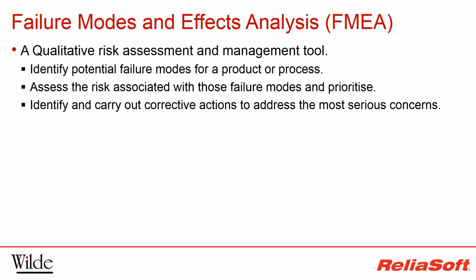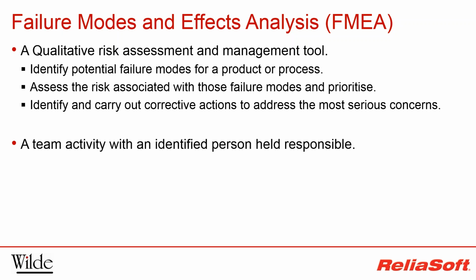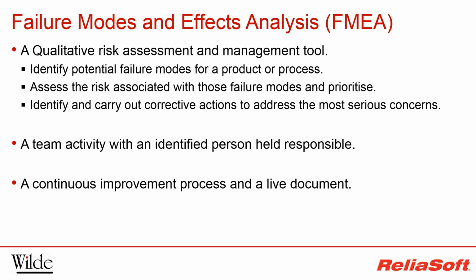Finally, based on the findings of the study, actions can be raised to deal with the most critical issues, with less time spent on issues that are of less concern. Although the FMEA is a team activity, it is important that one person is held responsible to ensure that the task is completed on time and to the required level. Furthermore, the FMEA should be treated as a live document, which should be reviewed and updated as the design develops.